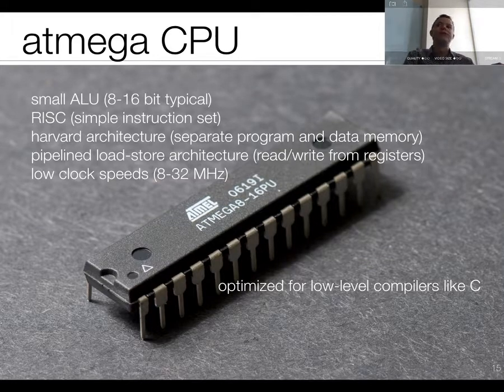However, you will still find a lot of people that want to program microcontrollers in assembly language. The reason they do that is to avoid any of those compile time operations, sometimes the optimizations, that bog this down just a little bit. So a lot of times if you're running, say, an FFT on a microcontroller, it will be written in assembly code to make it as fast as possible. So you call it and it comes back.